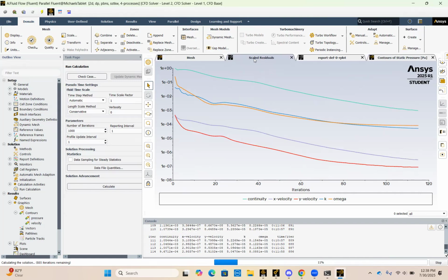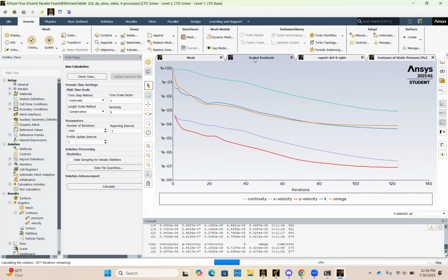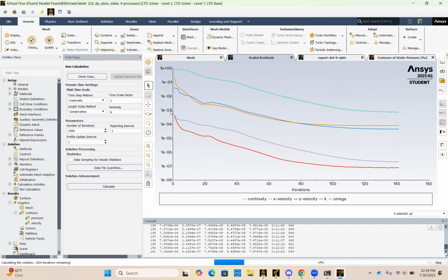Now you can set the line residuals to a different value for each line, but they're all 0.0001, as it has set. But say I left it at 0.001, it would be just about finished, because as you can see, our top line would be below. But since we lowered it, it's going to take a bit more time, so just give it a moment.